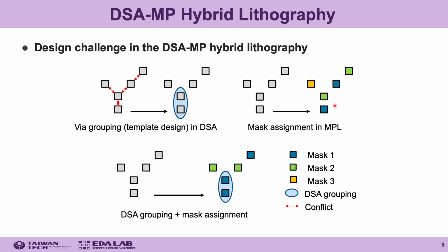By comparing the coloring solution derived from this multiple patterning lithography and that from the DSA multiple patterning hybrid lithography, we can observe that the advantage is that for the same via layout, fewer masks are required by this hybrid lithography.